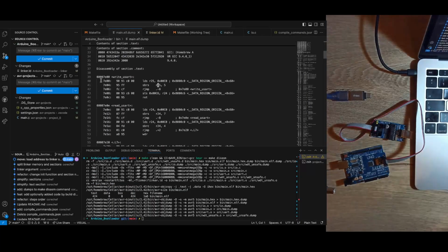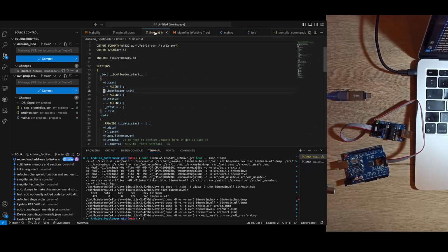So we're going to see that the program is shifted to the appropriate place, but the first instruction is not the one I want. So this is going to execute wrong, because the CPU, the microcontroller, is going to start at this address. It's going to execute this instruction, but it's just a utility function here. It's not the entry point of my program.